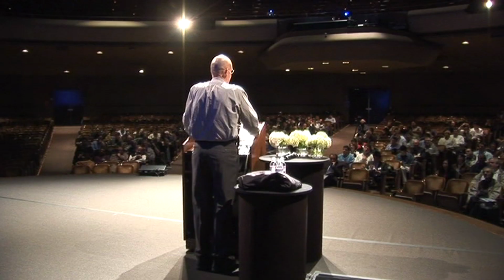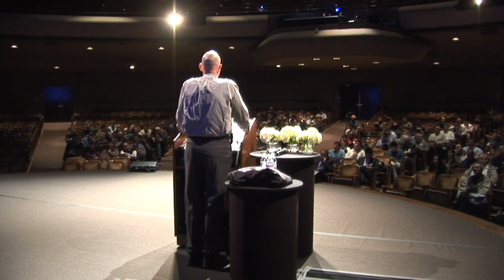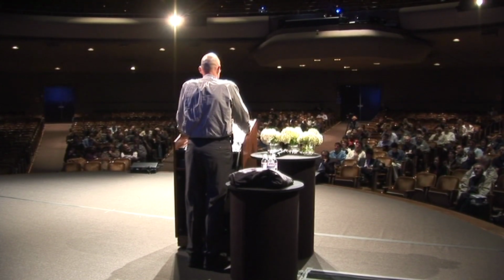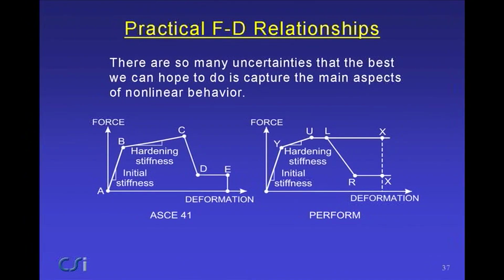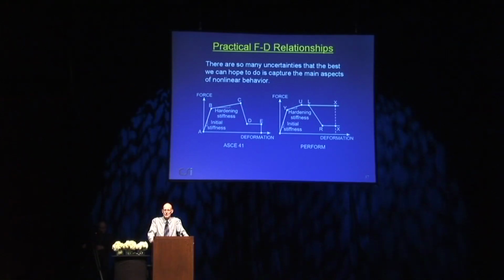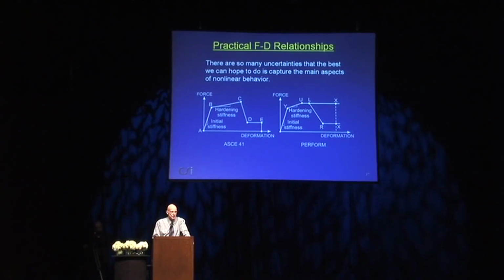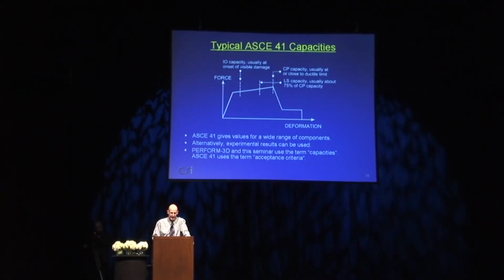There really isn't any point in continuing beyond point X. So if this was, say, plastic hinge rotation and point X were 5% hinge rotation, if you've got that much hinge rotation, there's no point really in continuing the analysis, you may as well stop. And that is what Perform uses the X point for mainly, to stop the analysis in case you get deformations which are unrealistically large.